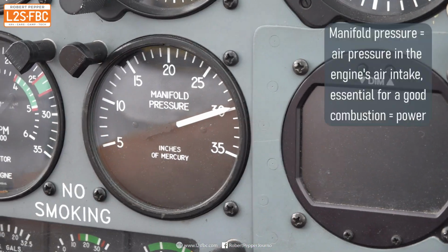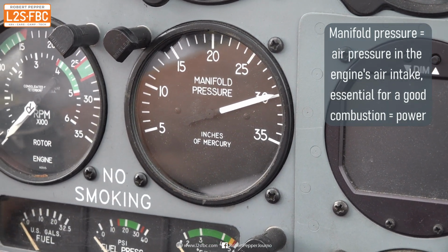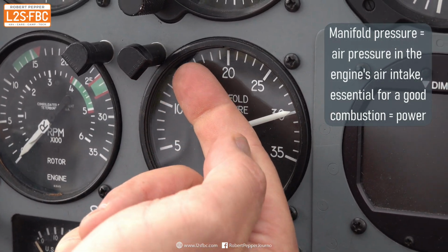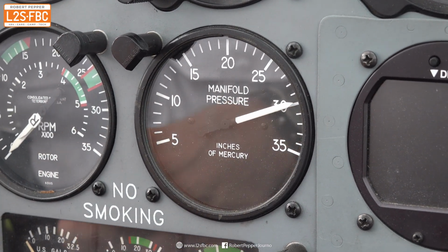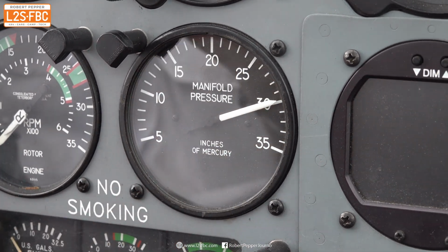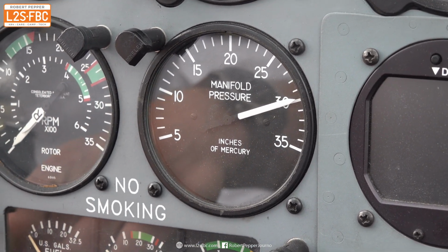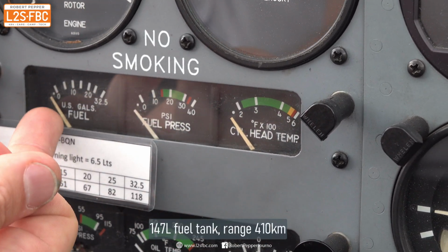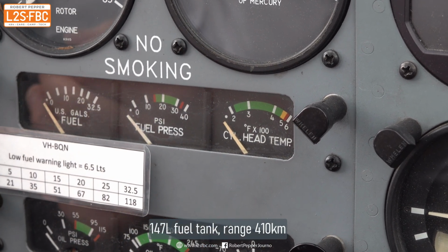Manifold pressure is a measure of what goes into the engine, the fuel and the air combined. When you increase the power, the needle will increase its reading. Now some people say, well, I haven't started the engine yet, so why is it pointing at 30 inches? That's actually the static ambient pressure around us, roughly 29.92 inches of manifold. And that's about it. Then we have a couple of gauges over here that give you the quantity of fuel, the fuel pressure, cylinder head temperature, oil temperature, and then a couple of switches.